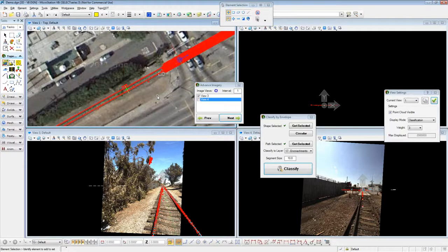When you say construction, is that existing construction, point cloud, things like that? Yeah, we went into a lift shaft that had just been constructed, and the designers wanted to know if the shaft construction, the concrete, was either inside or outside of a given tolerance. Oh, sure. It's about the path. If you can define the virtual path, where it should be according to design, this is a line down your shaft, and then you can make any polygonal shape you want, and it'll go along that path and classify anything that encroaches inside of that.